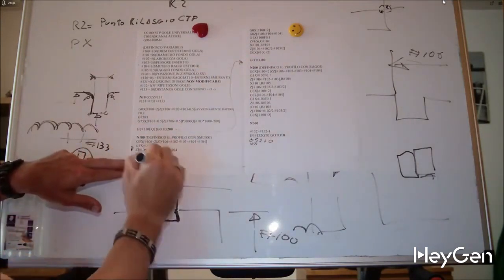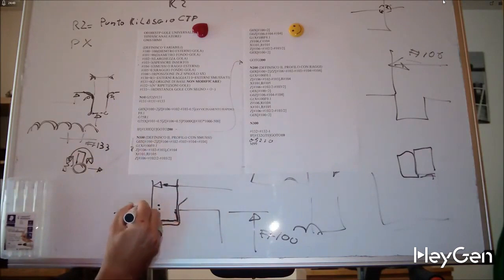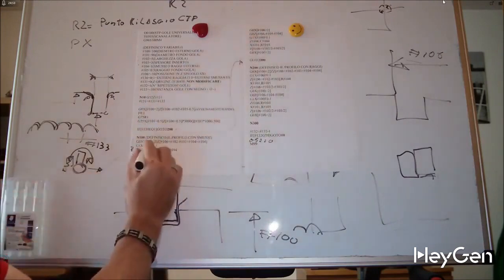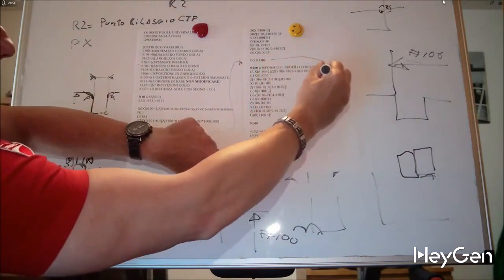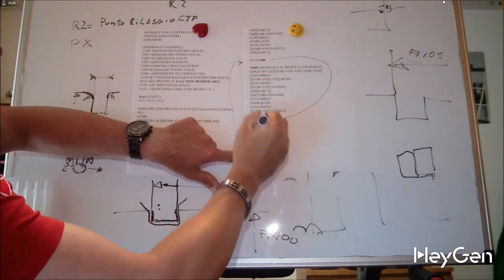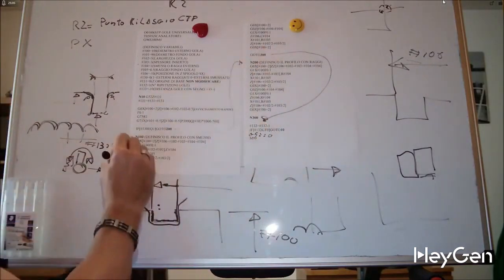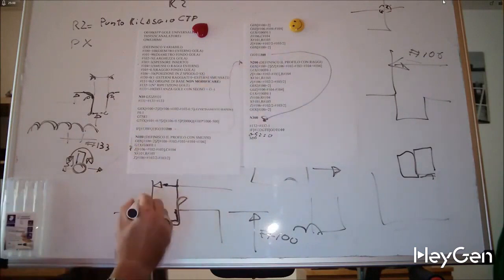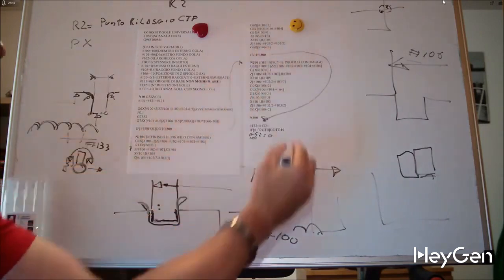This is the program that will finish the insert once I've executed it with the chamfers. I go to N300 and skip the execution of N200 because I've already done it. If I accept this jump, I go to N200, and instead of chamfers, I'll do some radii. So this area and this area are the finishing of the sides and the bottom of the groove.